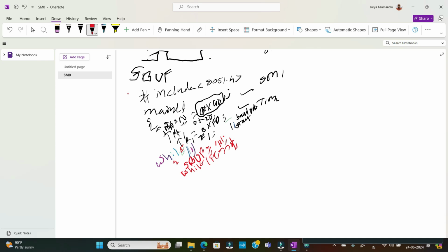Sir, why you are putting a semicolon? A while loop does not require a semicolon, right? But why you have kept it here means I have to wait here for some time until this TI becomes 1. Until this TI becomes 1, only then it indicates that the data is successfully transmitted. I will show this in the step-by-step execution of the program in the simulation part. But for now, you just assume that until TI becomes 1, we have to wait here only.